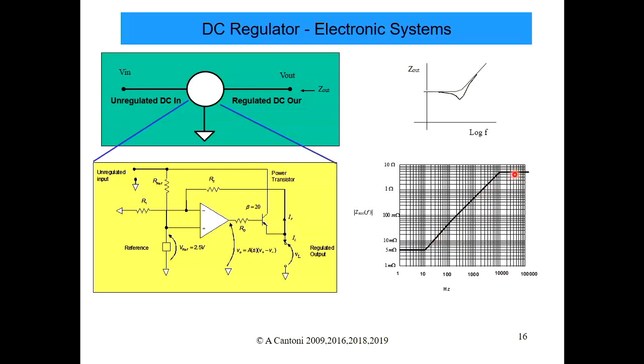So, it's a log-log scale, and you have basically the impedance increasing in a straight line. What could you model that system with in terms of bulk lumped components? What would be a good model for that regulator system? When we come to look at the system in its entirety, you wouldn't really want to have to model all the complexities there, but what would be a simple model of a couple of lumped elements that would represent reasonably well that particular characteristic? Anyone?